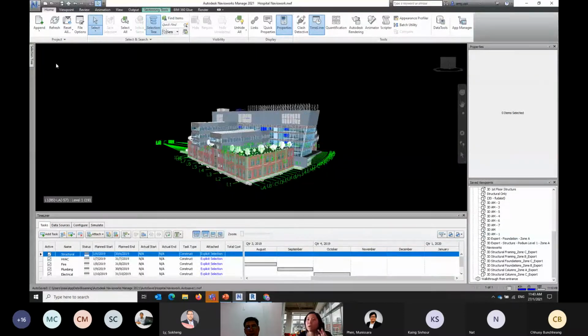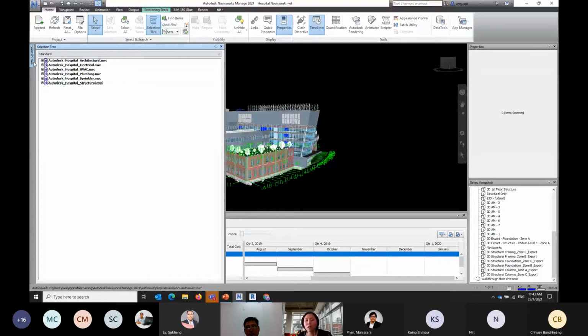So this is Navisworks. Now, why do some people use Navisworks? When do you actually use Navisworks? When you are the project coordinator, whereby you have to check the designs. You're not the person who's creating the designs, but you have to check the designs. So a lot of times this is after everyone has completed their Revit models, or when you actually want to begin construction, the contractor has to run a clash analysis on the design. This is when Navisworks Manage comes in.